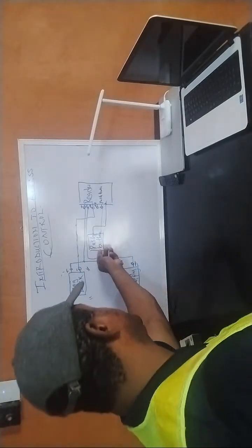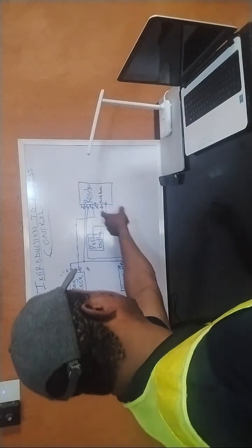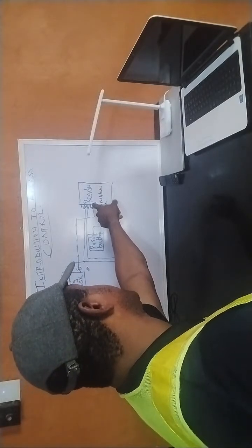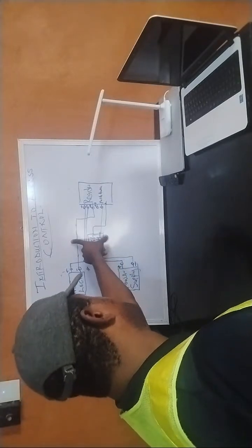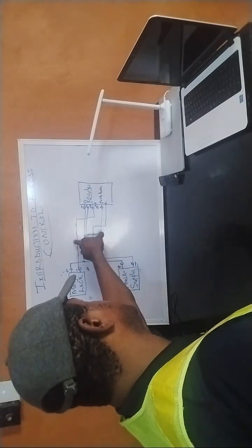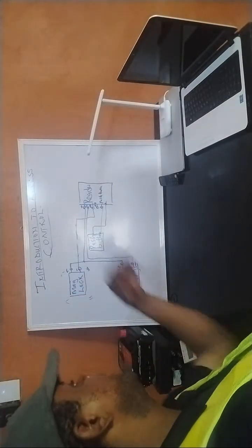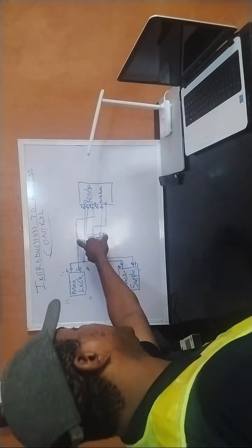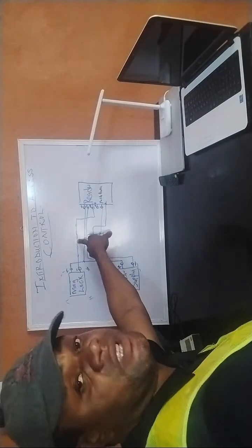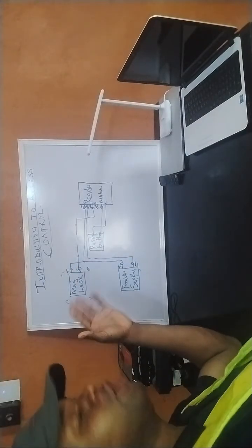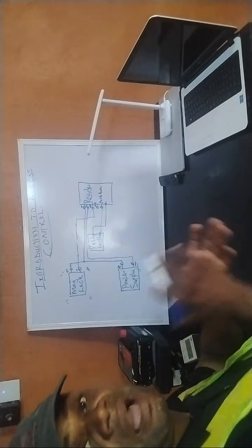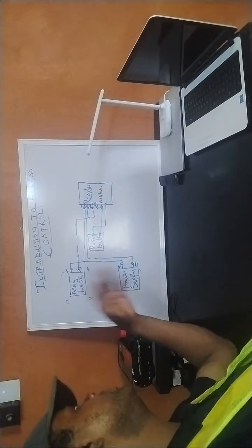By the time you push your push button, it changes this contact here. The normally closed becomes open. So by the time you push this button, it will cut this off again. But this one is inside the building, then this place is opened, and this coil de-energizes. So there is no magnetic field at that time, so you are able to come in through the door.